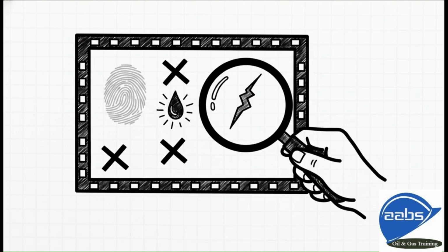Here's a crucial point. Before you ever reject a weld for a crack or porosity, you have to act like a forensic detective and rule out false indications. A dark line on the film might just be a scratch or a crimp from mishandling. A weird, suspicious blob could be a chemical stain or even a literal fingerprint smudge. You can actually even get false indications from defective intensifying screens inside your cassette. You have to definitively prove the indication is in the metal itself and not just human error from the darkroom.